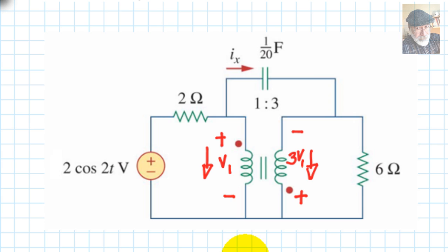And the current is higher on the lower side, on the left-hand side, and will be smaller on the high voltage side. It's unknown. I'm going to call that IA. So it's 3 times bigger on the low side. This is 3 times IA. We have taken into account the transformer's 2 equations.